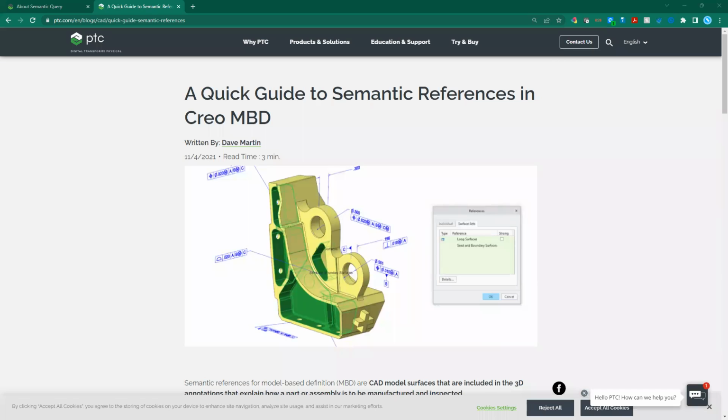I do see one other query here, around Michael Uhelke's question about understanding what tolerances would be necessary. Wouldn't the easy tolerance analysis tool be what he would need? It's a little bit different. What the easy tolerance analysis tool allows you to do is evaluate the impact of the tolerances that you laid out. It won't analyze the model and tell you exactly what you need to lay out.